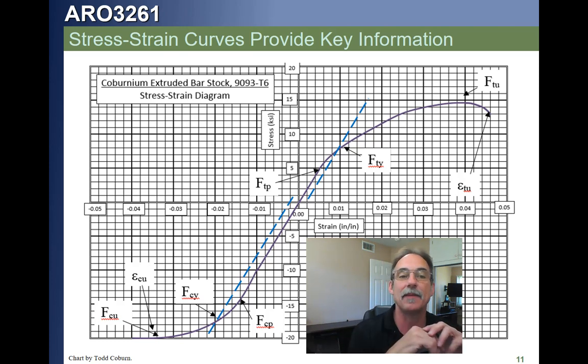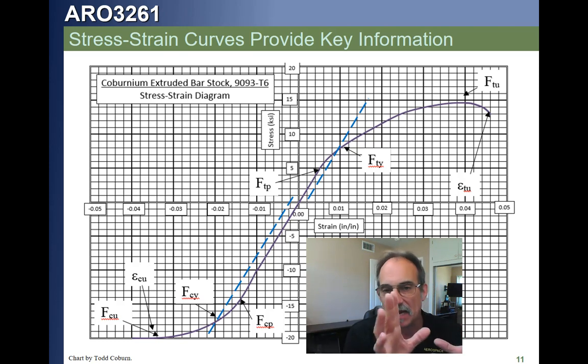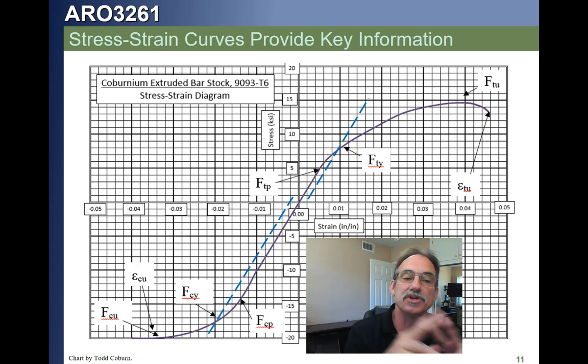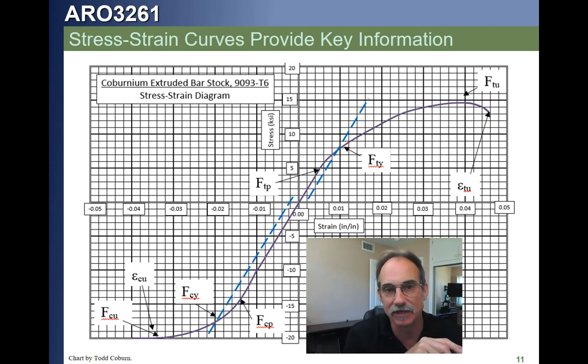And it's okay to pretend that, because most of the materials that we're going to use in engineering, the most standard materials, the steels and the aluminums and magnesiums and things, these all have stress-strain curves which are nearly symmetric. They're almost symmetric, which means the stress-strain behavior in compression is nearly the same as it is in tension. Now, it's not completely the same, as we will find out as we move forward.